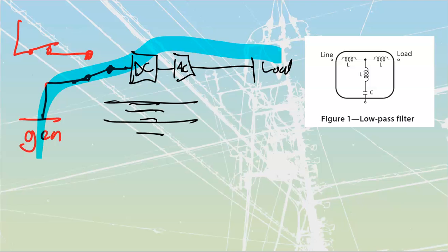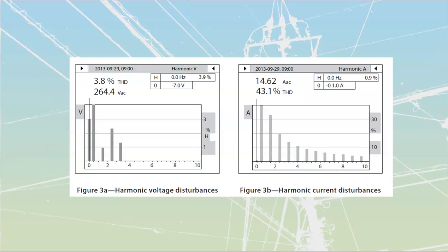When you do harmonic analysis, power factor, harmonics, etc., you're able to find out what the K ratings are going to be. All of these meters are going to spit out K ratings, and if the system says, hey, look, you've got a K rating of 3, you've got to match that with your transformer so that you are able to deal with that, because it's just telling you the size, or basically the scaling that we're going to have. Standard transformers have a K factor of 1. So just a regular old isolation transformer is going to be considered K factor 1. Anything that is overbuilt is just going to be multiples of that.